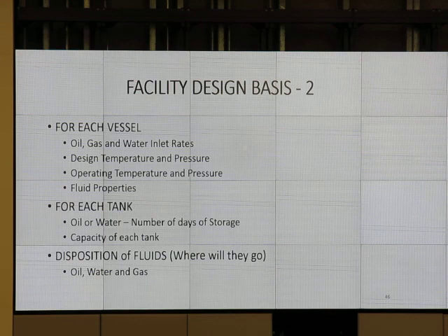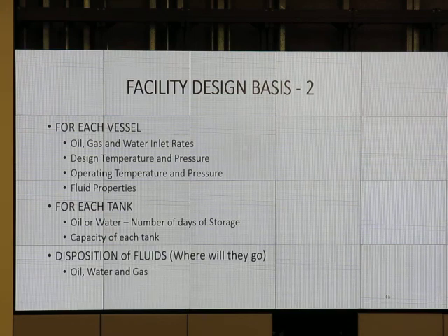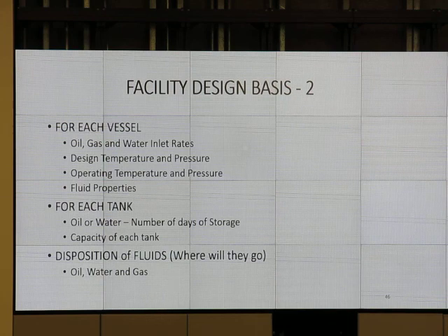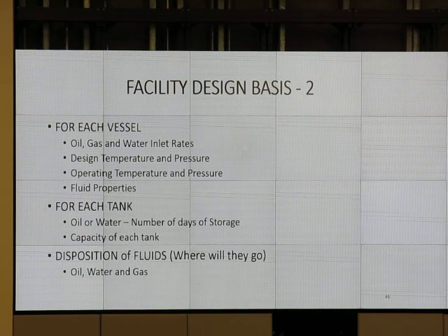If I need tanks fast, I'm going to have to put them on a truck. What's the biggest size tank I can put on a truck and deliver to site? Depends on where you live, but usually they're going to be 500, maybe 750s. And if I get bigger than that, I'm going to have to field construct it. Down in the Eagle Ford, I've seen 25,000 barrel tanks. In the Sahara Desert, we had 25,000 barrel tanks that we field constructed. That takes longer to build, so what am I going to have to do in the meantime?